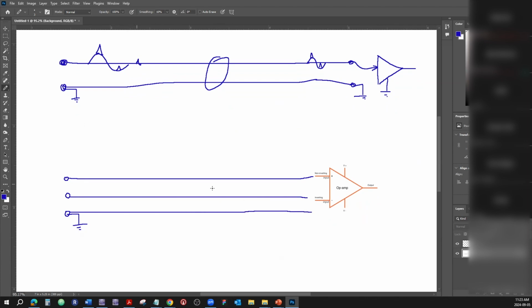Now, if we get a differentiated or balanced signal, it's very easy to make. All you have to do is get a transformer. Tap it in the middle, and you get 3 terminals. It will give you this here and here. So if the signal is like this here, we have an out of phase signal.